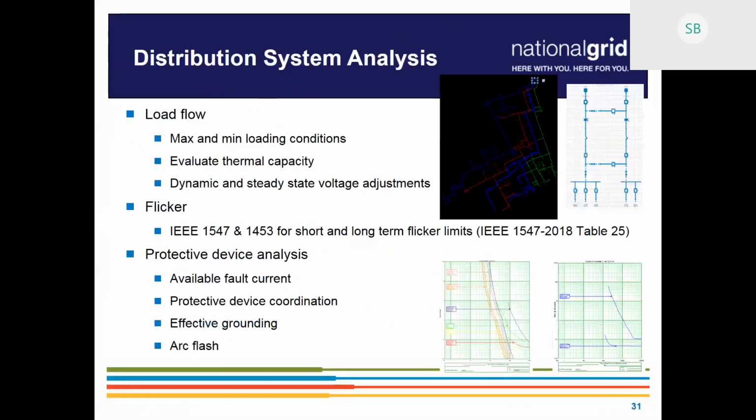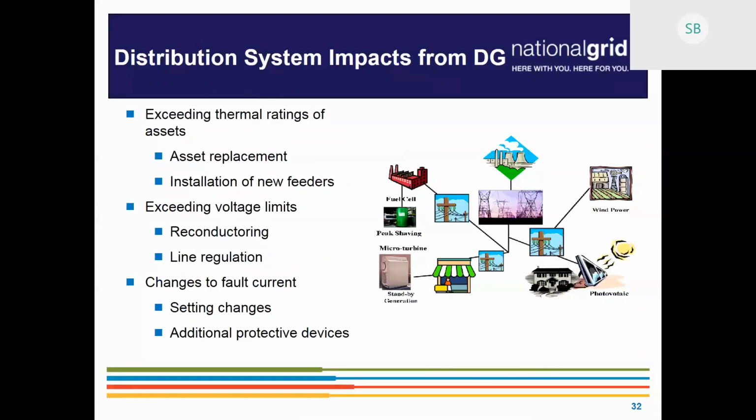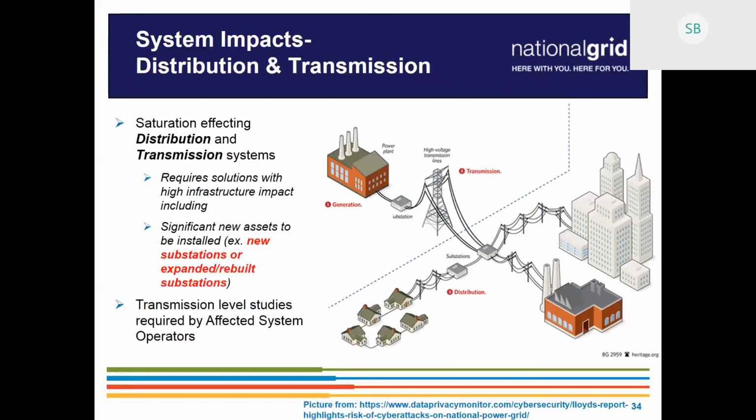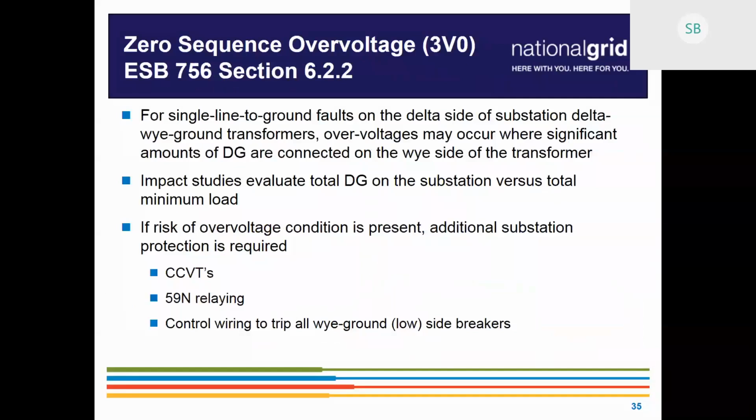Not necessarily, it would depend on a couple of different factors. For the means of effective grounding, we would look at it based on the site size, and if it was of concern, we would end up asking for it. So we reserve the right to ask for it between 250 and 500. Over 500, it has to happen. So that might be why you're seeing that comment that it may be required. There are instances where the screeners do talk with my group, and then we determine whether or not it is required before it goes out.